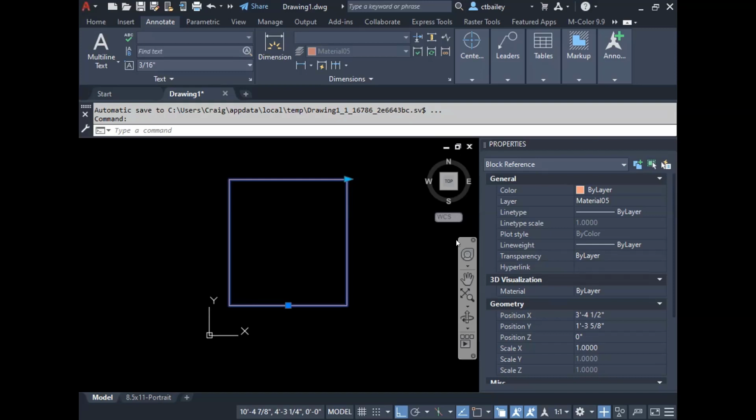Let me ask you this: what tool makes it move? What part of this makes that thing move? In this case, a change in width. Right, so then just select your stretch action. No, that's the parameter. These are your actions. See that box? Hit escape. Select that stretch action. That's the vertical. You attached to the wrong one. Delete that, remove it. Then just change it right here. Right click.